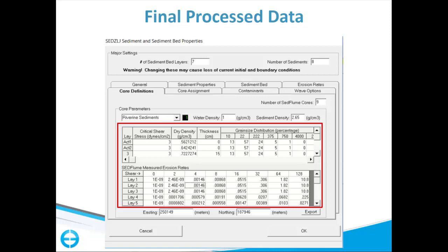So you may potentially either blend, or let's say you've got coarser data, you've got a layer that is 15 centimeters thick, and I have a measurement that represents 3 or 4 centimeters in your core. You may just apply that across a larger interval, because maybe later at a quarter of a meter depth you have another set of measurements. So you don't necessarily always sample every single interval all the way down in your cores. You might, but you might not.